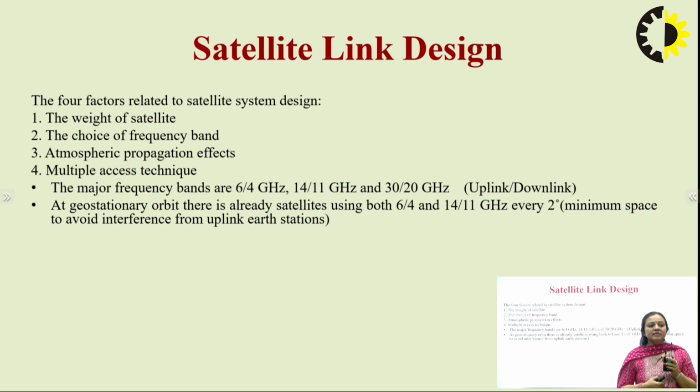So the major frequency bands that I use generally, as I have already illustrated in my previous lecture, are the C band for satellite communication. You can use Ku or Ka bands also. The major frequency bands are 6/4 gigahertz, 14/11 gigahertz, or 30/20 gigahertz.